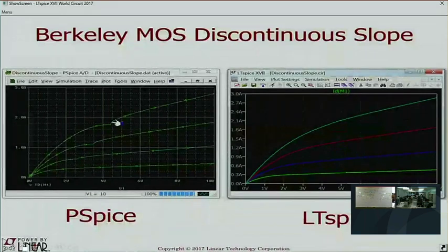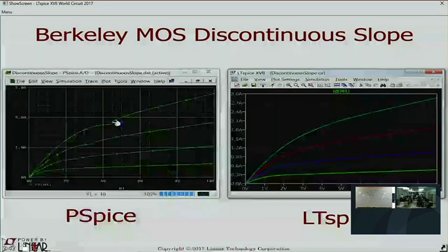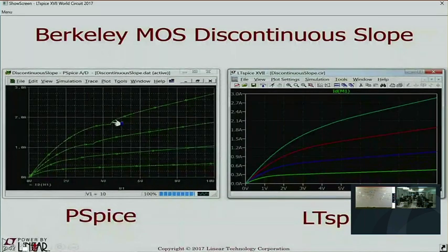You don't have to just make the IV curves continuous in value and slope. There are other types of singularities that come up. Say you want the drain current of a MOSFET. You might say the drain current is this function divided by that function, but you might have a point where they're both zero. The drain current isn't undefined, but the way you formulate it is undefined. How do you fix that problem? You apply L'Hopital's rule. You differentiate the numerator and denominator, and you have to trap it and deal with this. This is all very basic stuff.